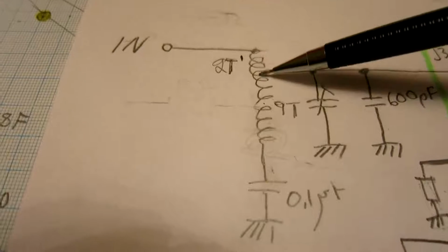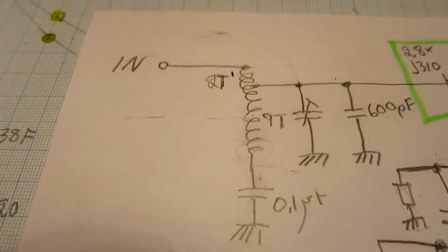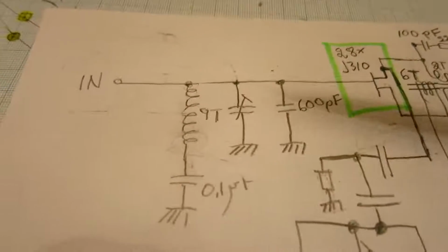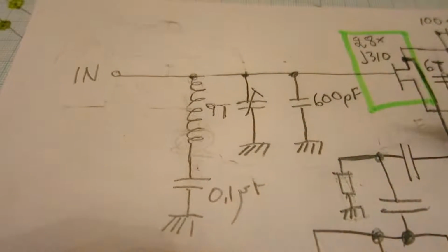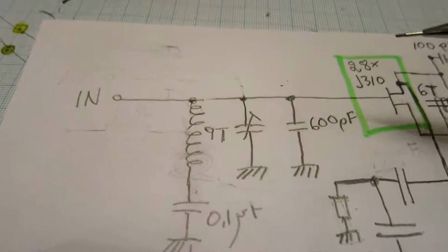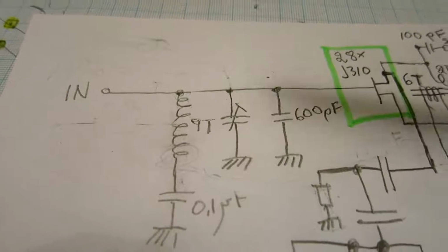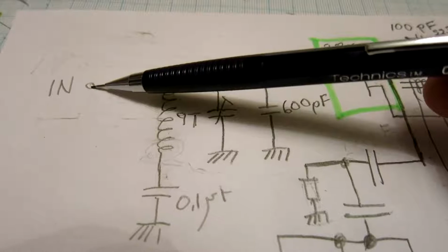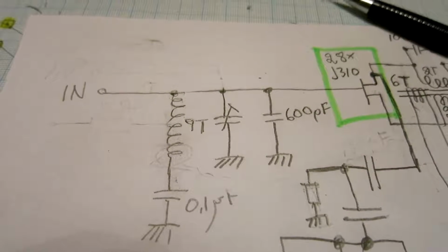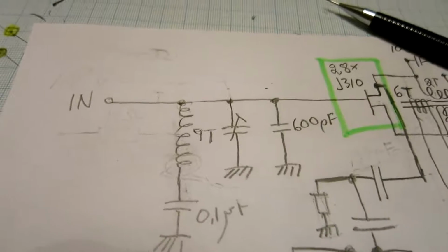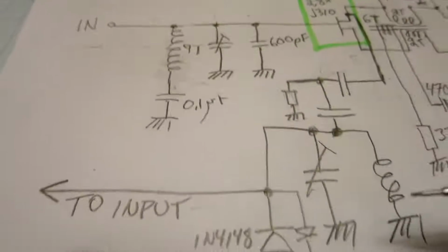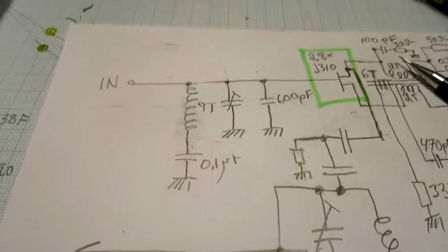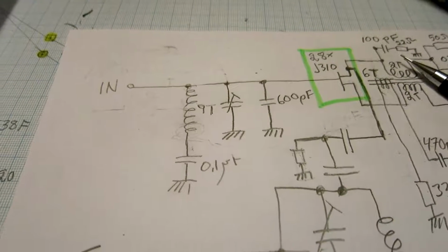I have removed this winding. Actually it was only one turn. This gives a little more signal into the power amplifier and that probably degrades performance a little bit at very wide frequency separations, where a little more noise from the wideband white noise from the pre-amplifier goes into the power amplifier. But the more signal here means the amplitude limitation becomes stiffer here. And that's what I want for the close range AM noise.